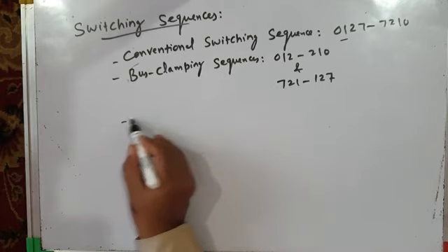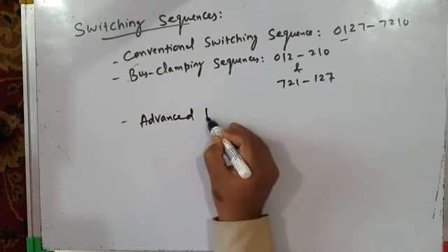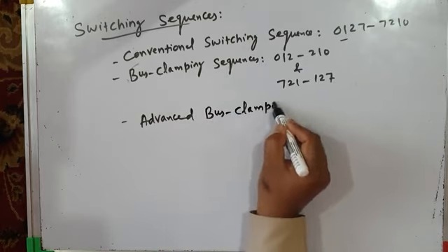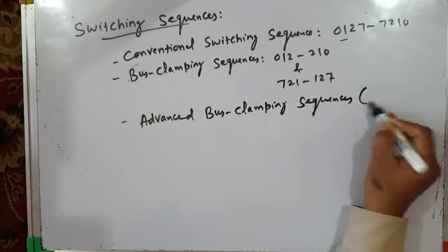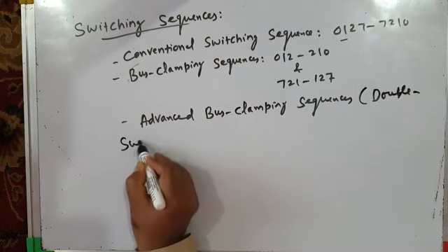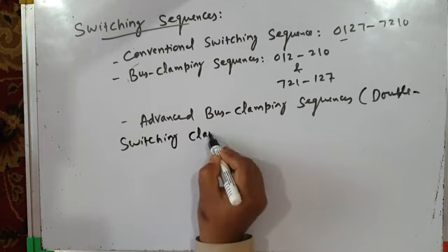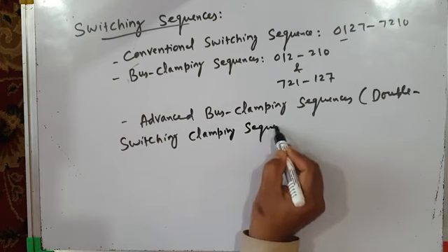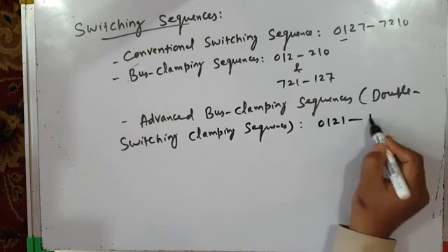And then there are advanced bus clamping PWM techniques, advanced bus clamping sequences, which are also called double switching clamping sequences. We have studied those also, like 0121, 1210.